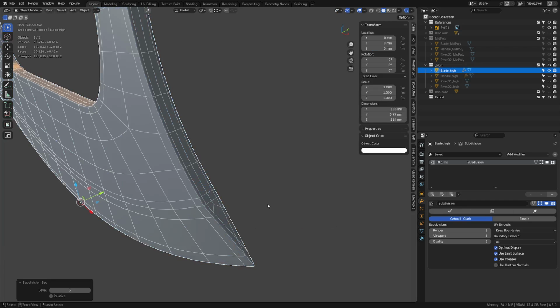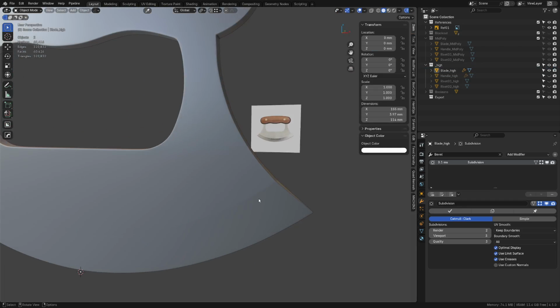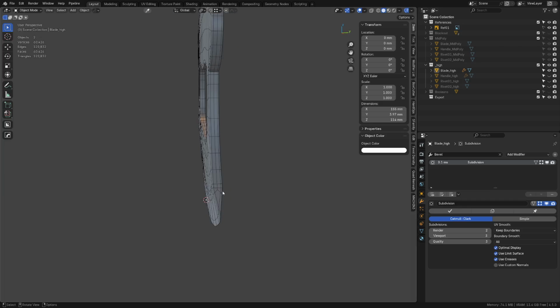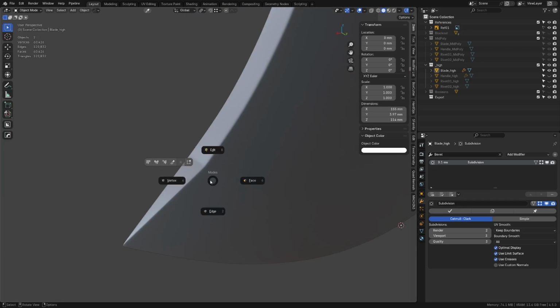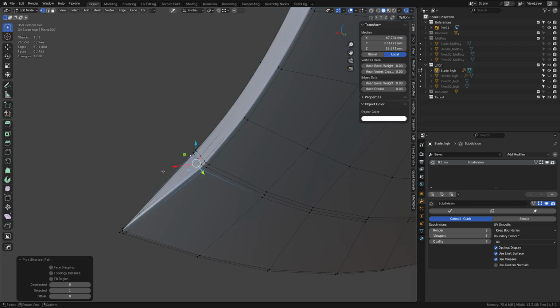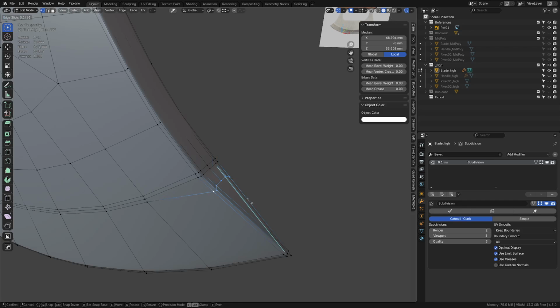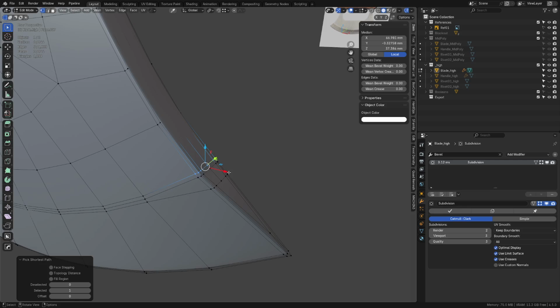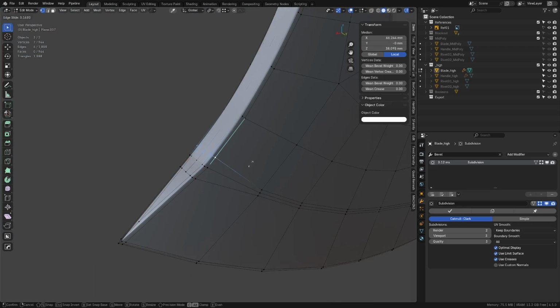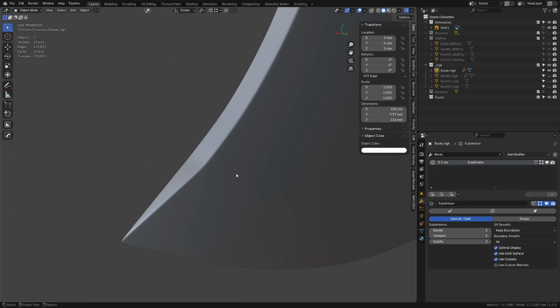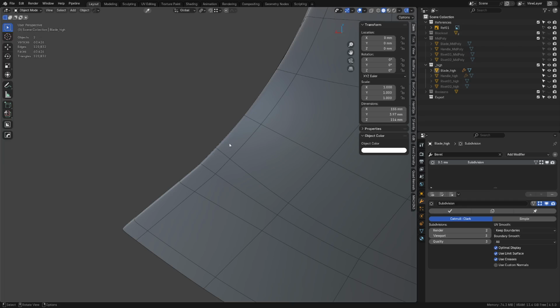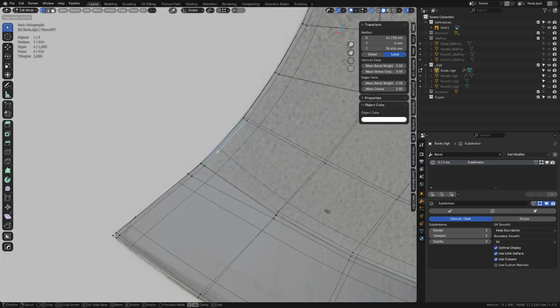right. So now we have that subdivision mesh. Pretty much the way we want, but we still have that sharp section. These we can bring down. You see they change shape. Press E and then hit F and try to keep it flat. And it's going to be even with that top edge basically. So we go through there, G twice, hit E, F as needed, and just space them out a bit, and it'll correct the curvature.